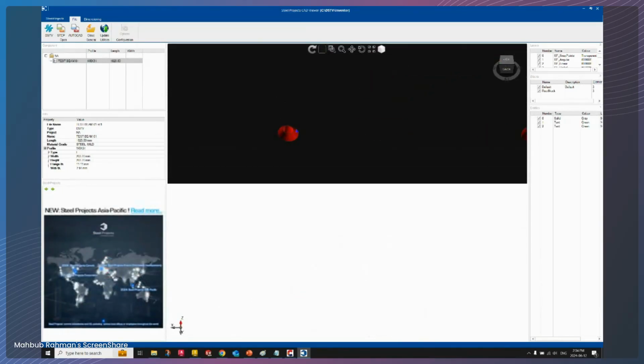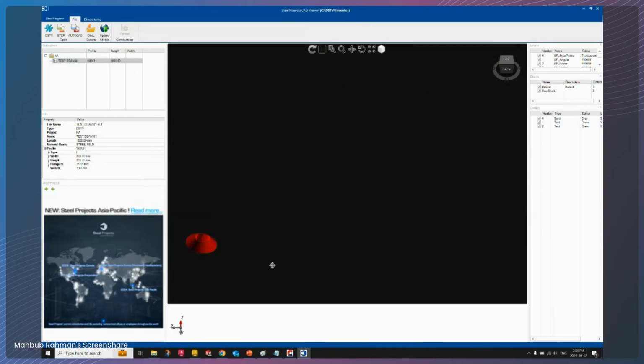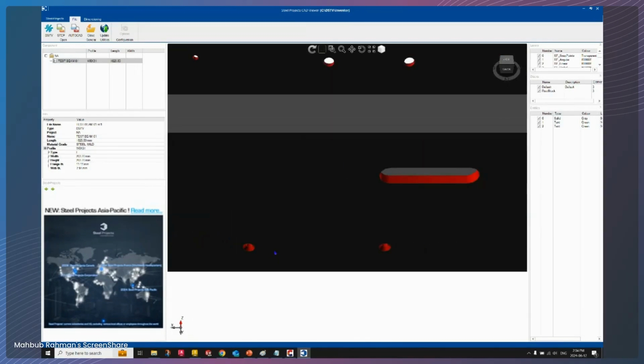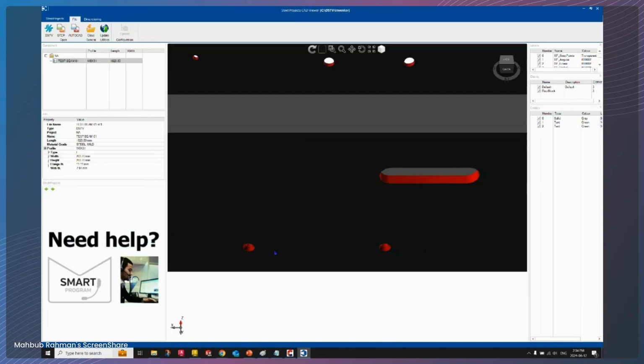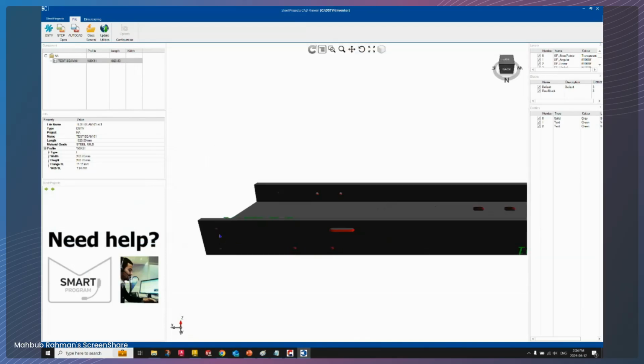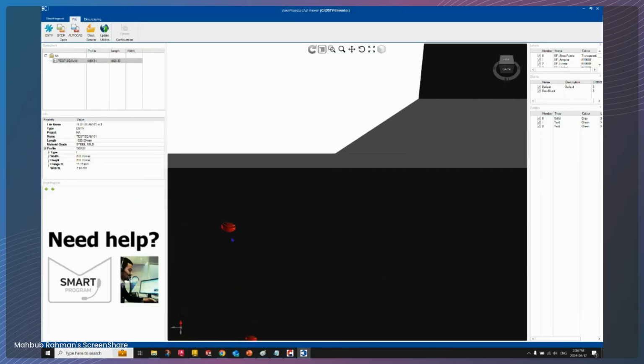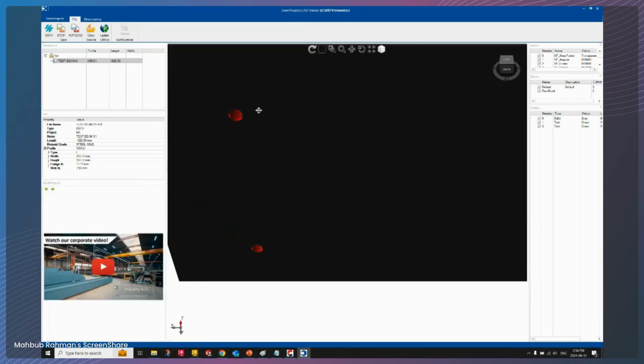And there you go. See that? Those are the drills. That's the countersink one. But our NC1 file is correct. Our CMS viewer is showing it as a wireframe, so that's why you don't see it. But it's there. At the same time, if I just zoom in here, see that this is the thread hole that you have over there as well, right?